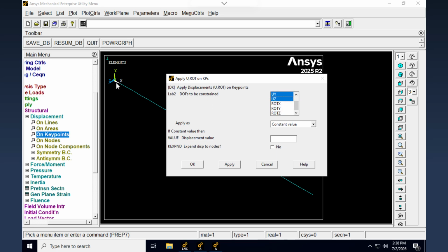Rotation about X is like torsion, like twisting, so I'm gonna close that. But about the Y-axis and Z-axis, I'm gonna let that get sloped. You see what I'm saying? I will let slope happen. So everything else, I'm gonna zero it.